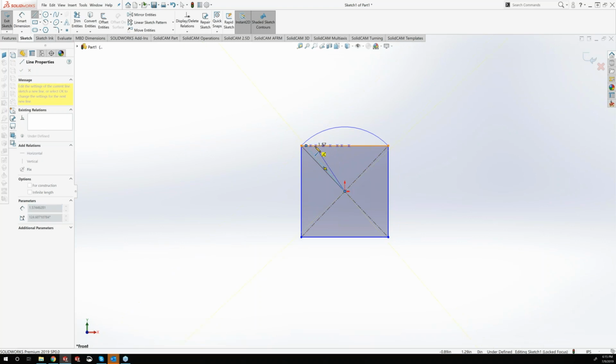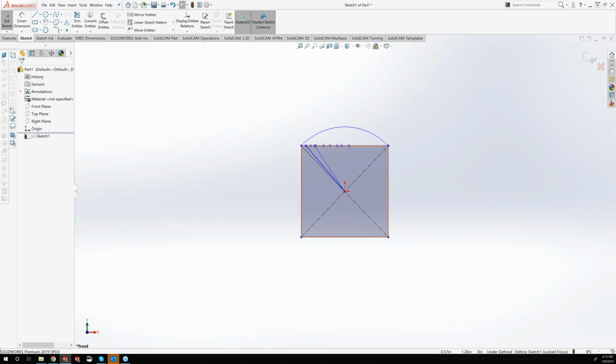That means that we get the tool to update at every single node point, which means that we can approximate this straight line as the tool is going around much better than if it is unchecked. So anytime you're doing anything that is polar, you're going to want to make sure you have as much point data as possible. Now, I think where Kevin was going with that is because you're putting in tons and tons of point data, you're going to have a huge file.